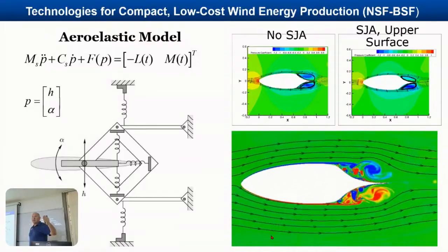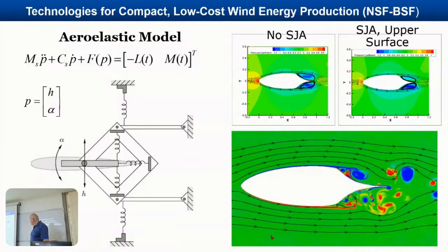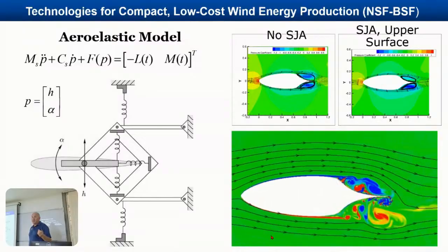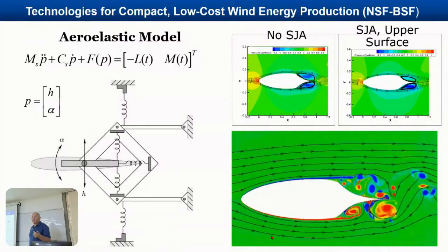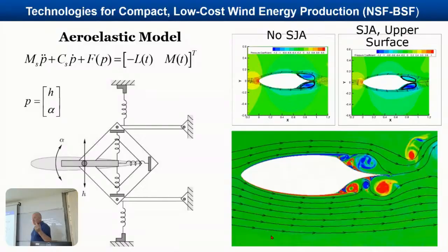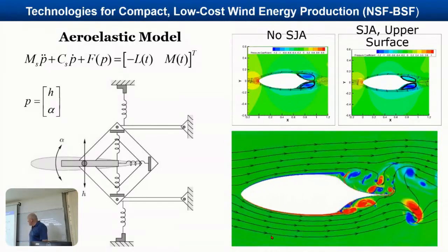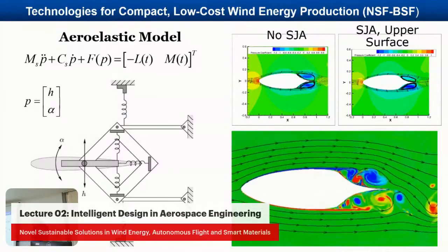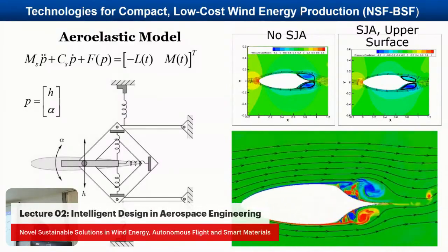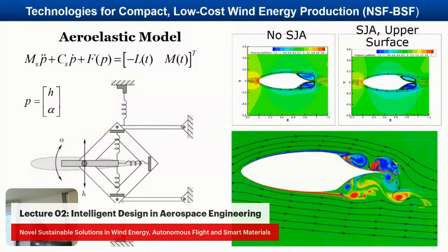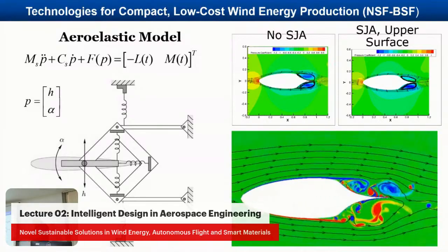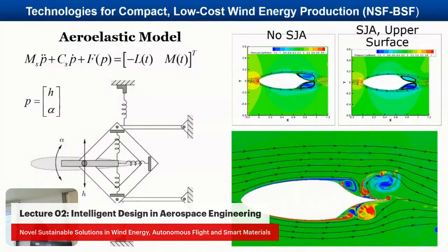So we usually investigate LCO. That's what we're working on. We don't want to have flutter. If you have pure flutter, the system will not work, because it fails right away. So you should be careful with these things. So this is LCO. You see it goes up and down with more or less the same amplitude. But this is actually uncontrolled right now, because you see it kind of goes, and then it's very hesitant to go.